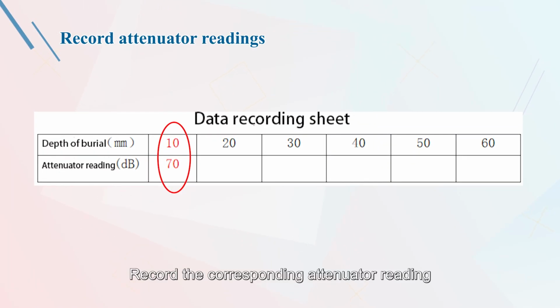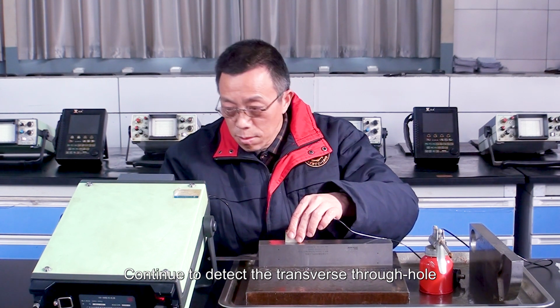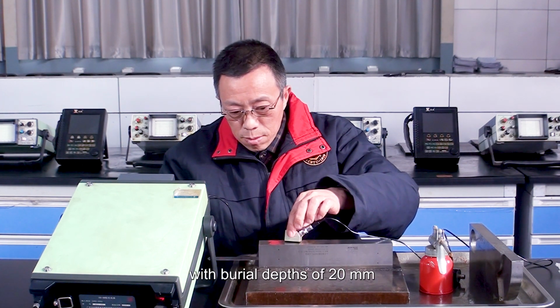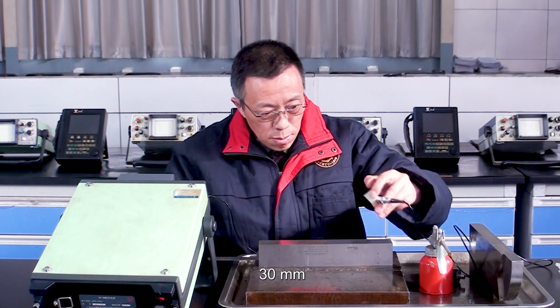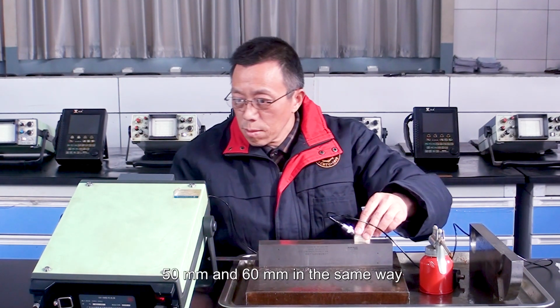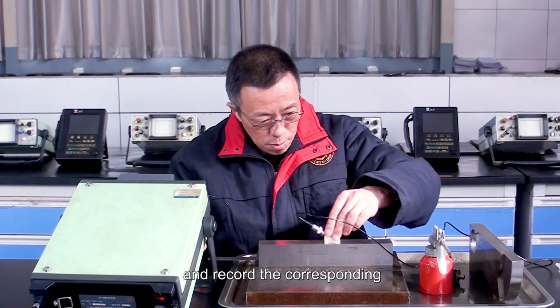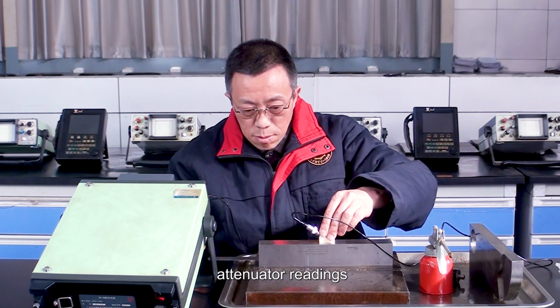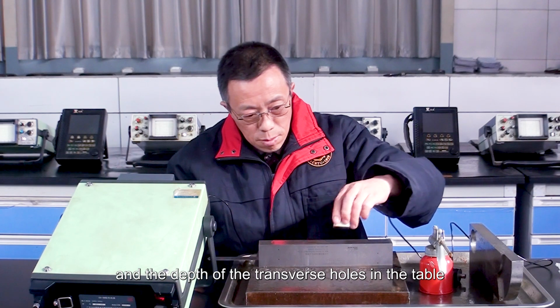Record the corresponding attenuator reading and cross-hole depth value in the table. Continue to detect the transverse through holes with burial depths of 20 mm, 30 mm, 40 mm, 50 mm, and 60 mm in the same way, and record the corresponding attenuator readings and the depth of the transverse holes in the table.